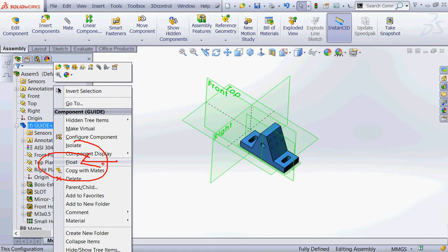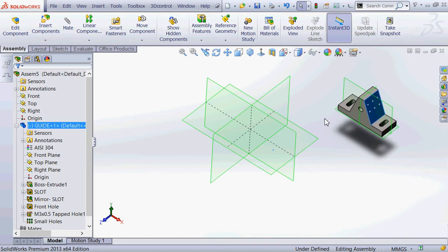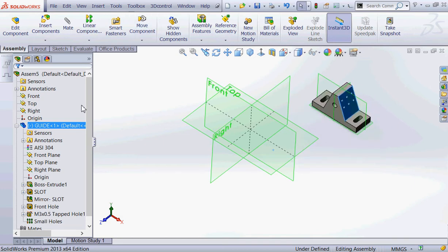So this is like, if you really want to piss people off, don't do what I'm telling you. This is best practices. So how do you fix it? Because remember, this says F, so it's fixed in place. It's grounded. It's fully constrained. It has 0 degrees of freedom. And notice right down here it says fully defined, right? So fully defined means it has 0 degrees of freedom.